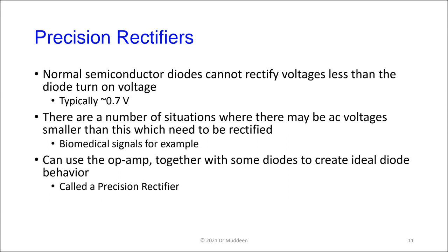It's such a fantastic device, and the whole crux of the matter is that the op amp has a lot of feedback inside of it. You remember we mentioned feedback with a power supply, and we'll talk about it more formally in a few weeks' time when we talk about feedback amplifiers. But feedback allows the output of the op amp to try to track the input as close as possible. And then the massive gain of the op amp creates that situation where the two inputs try to track each other as well, creating that virtual earth behavior that we spoke about.